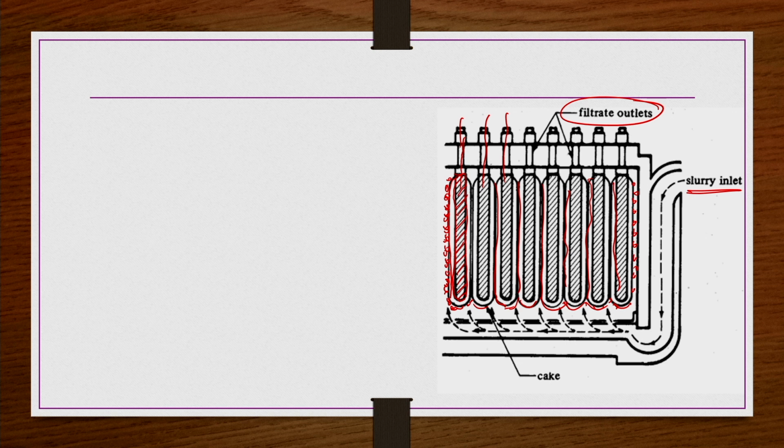So, now how to clean them? The easier one, since the cakes are deposited on the filter medium surface, what you do is, in the reverse direction, you blow some kind of air into the internal filter structure. The internal hollow screens are forming a kind of leaf, you blow air or some liquid under some pressurized conditions.